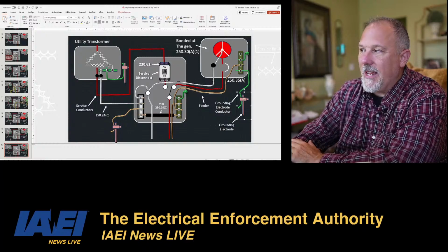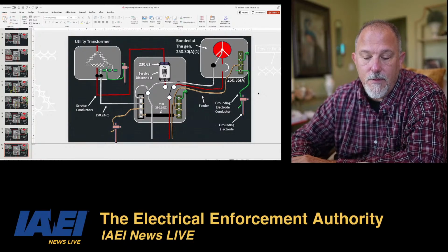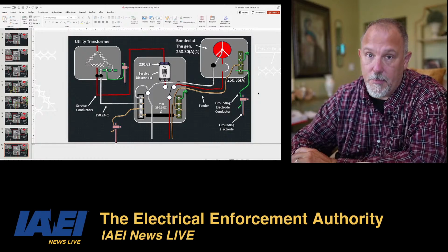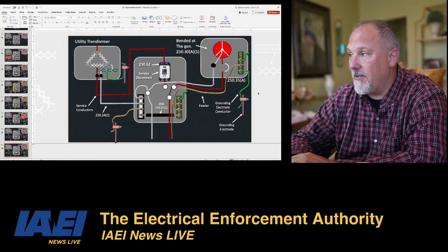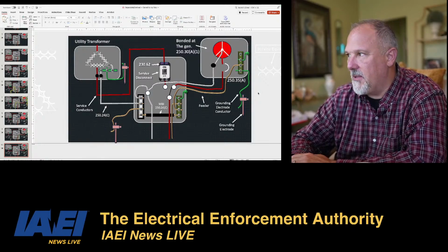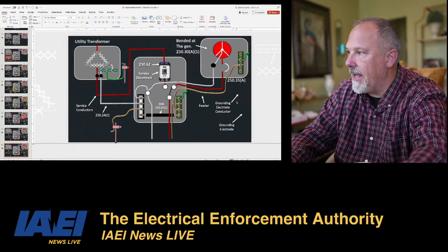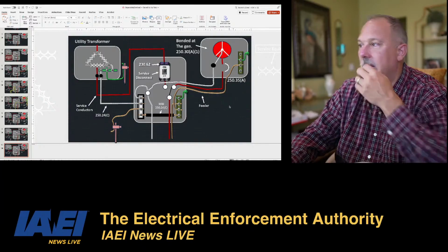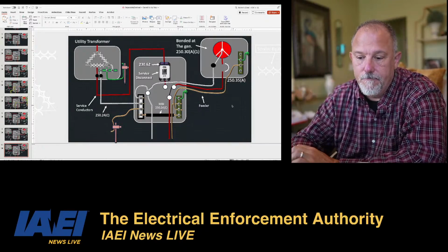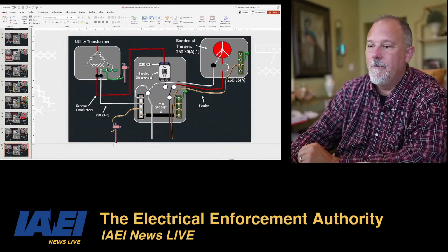Now you may say, well, I drove a rod and everything. Well, yep, you drove a rod. You can leave the rod there. There's nothing that prohibits you from having a rod, grounding electrode conductor and a grounding rod and all that good stuff. There's nothing that prohibits that. You don't need it. So what you could do as well is delete that and delete that. And now you still have a code compliant application. Laurel, yes, 110.3(B), manufacturer's instructions. In fact,